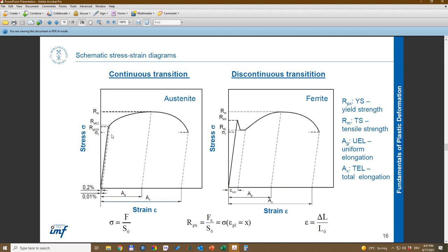I just did this in Excel, and this is how. So I removed this part of the curve, I converted it into a flow curve, and then calculated how much was the actual strain in the material, what is the 0.2% of that strain, and then just saw the point at which that strain occurred, and that was my yield point.